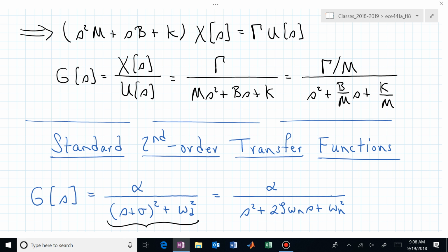We can now say, oh, I have a numerator, and I may say this is a pure two-pole system, meaning I do not have any zeros in the numerator. If I say a pure two-pole system, I mean I only have two poles in my transfer function. I obviously have some non-zero coefficient upstairs in the numerator, but there are no s's floating around, no finite values of s in the numerator.